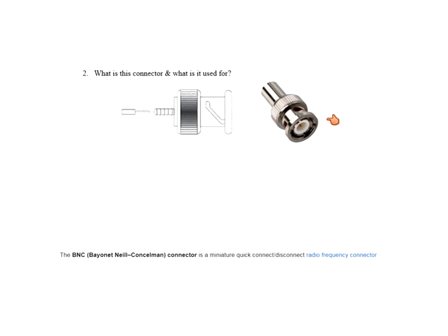Have you not seen that on the end of your O-scope probe? Well, on your own scope, you have something called a BNC. Quite often, the BNC is called a British Naval Connector. In reality, it's not a British Naval Connector, but it's a Bayonet Neill-Concelman. That's the actual name of it. So that's a BNC. That's typically used as a radio frequency connector working in the megahertz range, maybe 100 megahertz, maybe even up to a gigahertz. But it's used for all kinds of communication equipment, mostly for test equipment, though. You almost always see it first doing some kind of tests when you work with it.